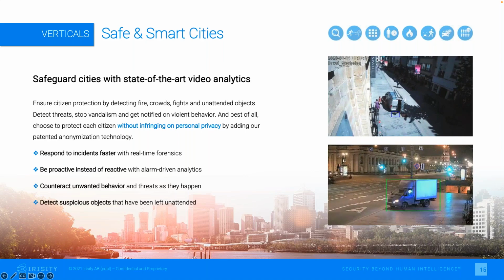But not only that, we can stretch through to identifying the number of people in areas and then linking that to the HVAC systems to make sure that the utilization and energy efficiency of that building is improved. For instance, if you have an area on a day-to-day basis that only has an occupancy of about 5 to 10 people, the HVAC system gets notification and you don't need to send as much cool air to that area.